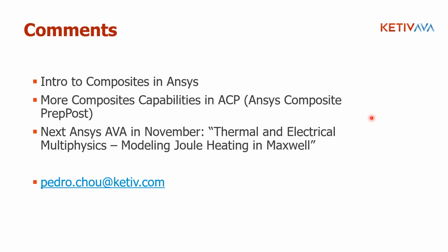And then from ACP, you bring the resulting composite to Ansys Mechanical, and then you do the analysis in Mechanical. And once you have the results, you can go back to ACP, and then Tsai-Wu, Hashin, all the other failure criteria that I showed you in Ansys Mechanical, where you need to define APDL, all those post-processing options are available in ACP. So ACP is a lot more powerful than Ansys Mechanical for composites. Okay. And yeah, I encourage you to look into ACP.